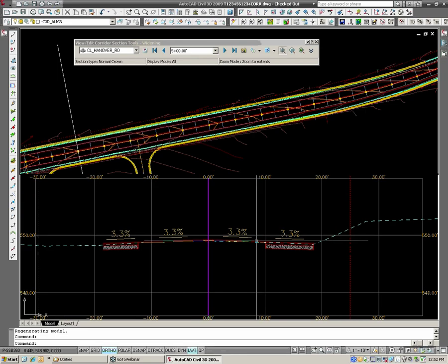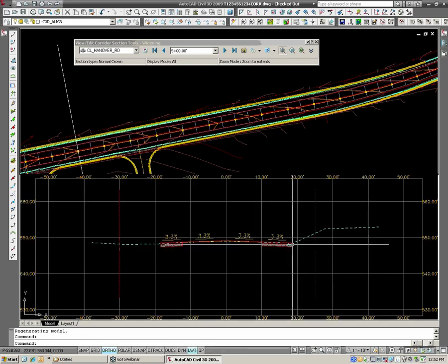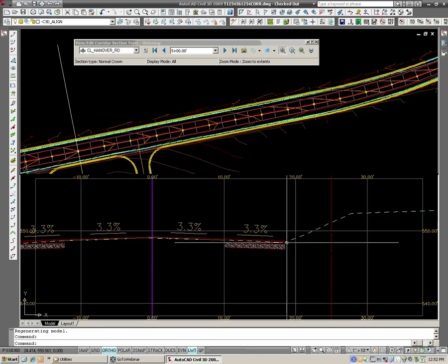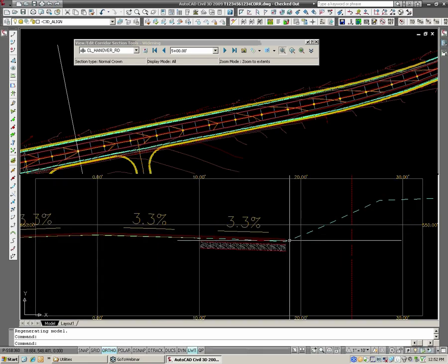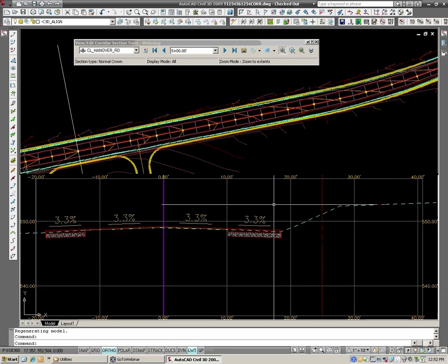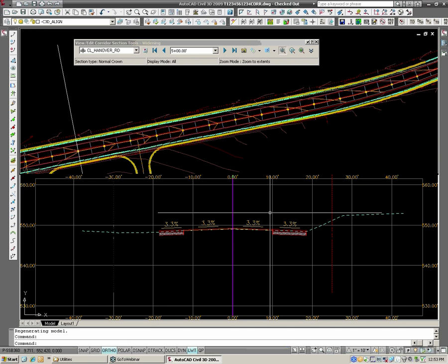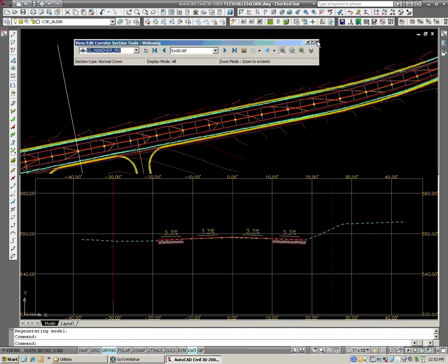And that is an awful nice thing when you're making design edits to your road, because you have to stay inside that alignment. So when you see projected slopes out, you can see from here, I need to pretty much come off this edge and project the grade. On this project, we add in a shoulder. Well, adding in that shoulder is going to push me outside this right away. So let's close off this class here with adding in that shoulder.